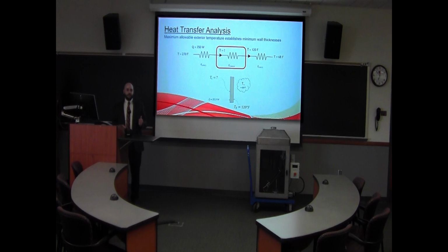We've got a flame at a given temperature for a given amount of time, and using that information, we determine what the temperature of the air could possibly be. Then we use a heat transfer analysis at a stable rate to determine how the heat propagates through the cabinet. Doing that, we used a heat resistor network. The simplified one is presented here. The more complicated one we simplified down by removing the insignificant components. Here you see the interior maximum temperature of the cabinet through to the exterior surface of the cabinet.